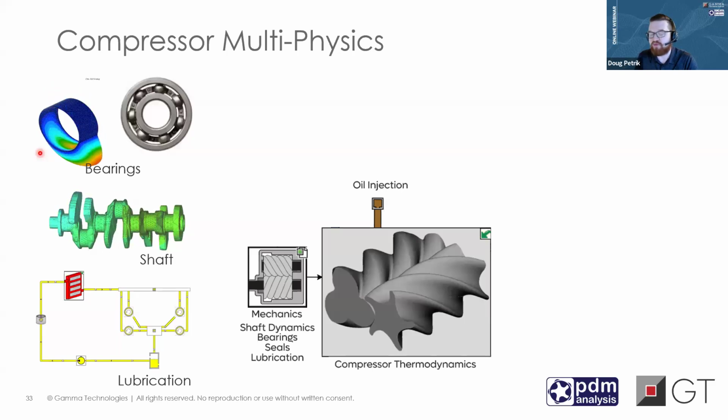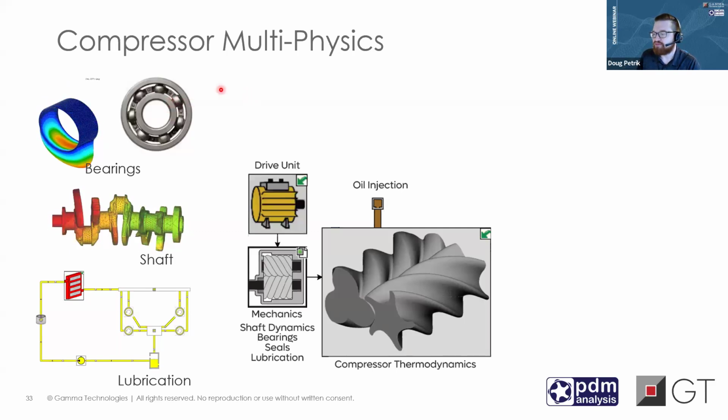And I want to point out our finite element bearings are EHD capable as well, and also support oil refrigerant mixtures if that's something that is of concern. We also have a roller bearing solution, which is based off the SKF catalog that can be utilized.